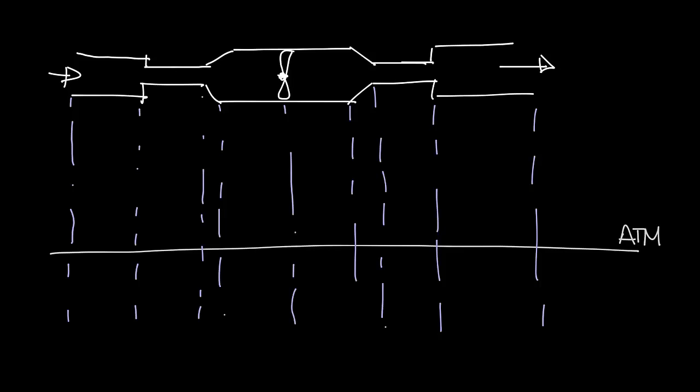So now let's look at the total pressure as the airflow goes through the ductwork. So we're starting at atmosphere because you're pulling from outside the space. So you'll start about here at the inlet of the system. It's going to come in, I added a little bell mouth, so it'll come in there. There'll be a little bit of pressure loss. Then it'll go down the duct. There's a transition, so there'll be more total pressure loss, a little more straight duct, transition, so a little more total pressure loss. Then it gets to the fan, and the fan boosts the pressure up here to above atmospheric